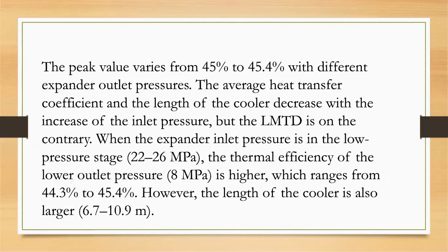But the LMTD is the contrary when the expander inlet pressure is at the lower pressure stage, in the range of 22 to 26 megapascal. The thermal efficiency at the lower outlet pressure of 8 megapascal is higher, ranging from 44.3% to 45.4%. However, the length of the cooler is also larger, 6.7 to 10.9 percent.